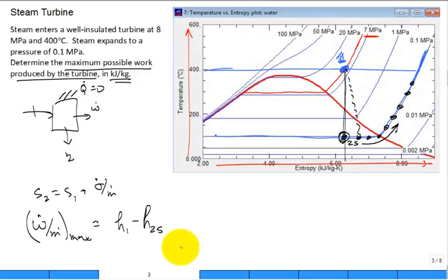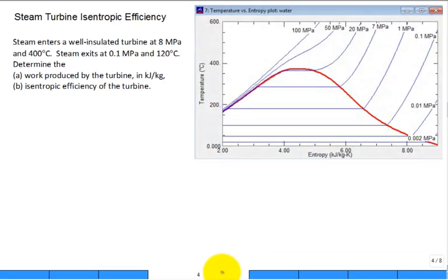Sometimes in the steam tables it's a little tricky because you don't know if it stayed two-phase or if it went out in the superheated vapor on the exit. You know, if it stayed two-phase with a pretty high quality or if it went slightly superheated. Sometimes you have to iterate. What happens if they tell you it exits at saturated steam? No, at 120. Actually, this is going to be close to 100. Let's say it exits right there.